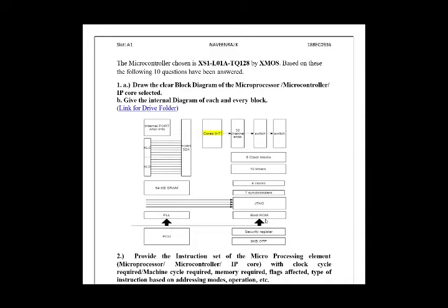So now let's talk about JTAG. JTAG can be used for loading programs, boundary scan testing, in-circuit source level debugging, and programming the OTP memory. It consists of so many pins: TRST_N pin, DEBUG_N pin. There are a lot of pins, and it is used for boundary scan testing and loading programs into OTP registers and so on.